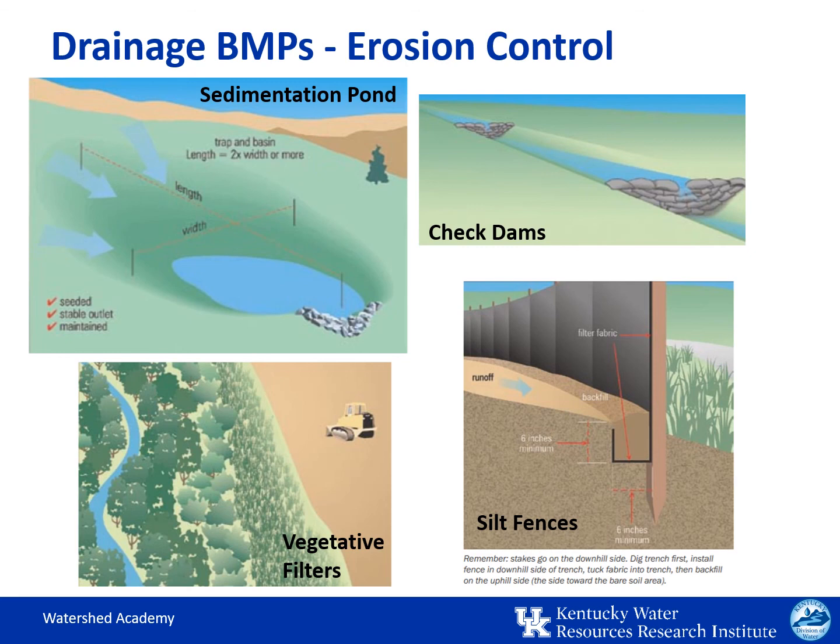Channel protection, including check dams, are measures used to stabilize channels against erosive forces. These runoff channels can be lined with grass, rock, riprap, or concrete. They can also be protected with check dams to reduce the velocity of stormwater runoff flows. Dams can be constructed of straw bales, lumber, or rock. However, straw bales are not generally recommended due to their tendency to decompose and fail.